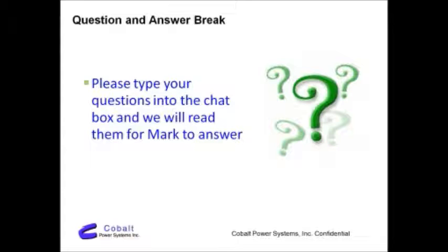Everything from, there's no conductors on the front of the cell. So if you imagine a cell, which is really the horsepower of a solar panel, most cells, like the Sharp cells that we looked at pictures of, have conductors on the front. SunPower has no conductors on the front. It's just silicon, and all the conductors are on the back, and that's one of their 120 patents.